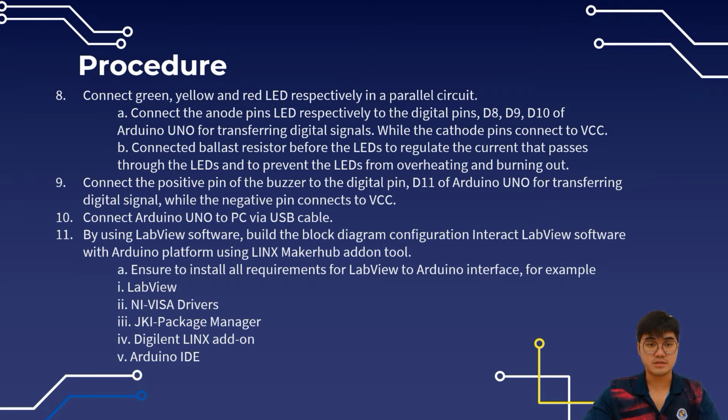And next, connect the green, yellow, and red LEDs respectively in a parallel circuit. Next, connect the positive pin of the buzzer to digital pin D11 of the Arduino Uno for transferring digital signals, while the negative pin is connected to VCC. Connect the Arduino Uno to the PC via USB cable.